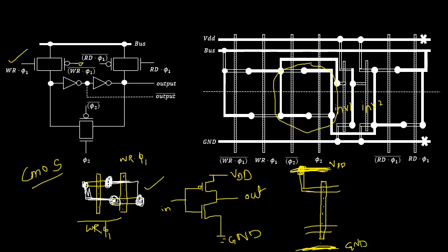So from here, that is the drain terminal to drain terminal, you are using a contact as well as the metal layer like this, and you are going to connect it to the output. Whereas here this terminal will be applied to the ground layer by making use of a contact cut. Since it's a CMOS design style, you have to use an N-well contact as well as P-well contact by marking a cross mark over the VDD as well as the ground, that is called as supply rails. So one CMOS inverter will be drawn like this. So that is what we have drawn in this particular inverter 1.